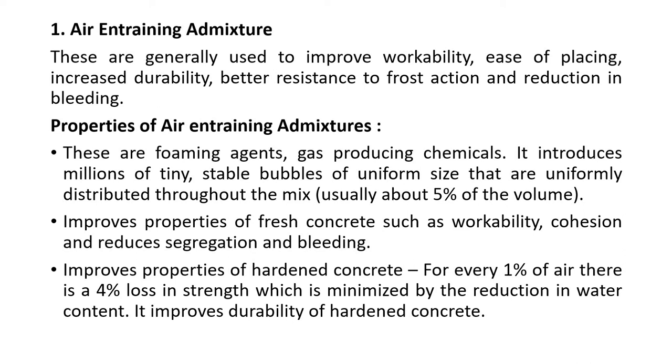Air entraining admixtures are generally used to improve workability, ease of placing, increase durability, give better resistance to frost action, and reduce bleeding. Properties of air entraining admixtures: these are foaming agents, gas-producing chemicals.